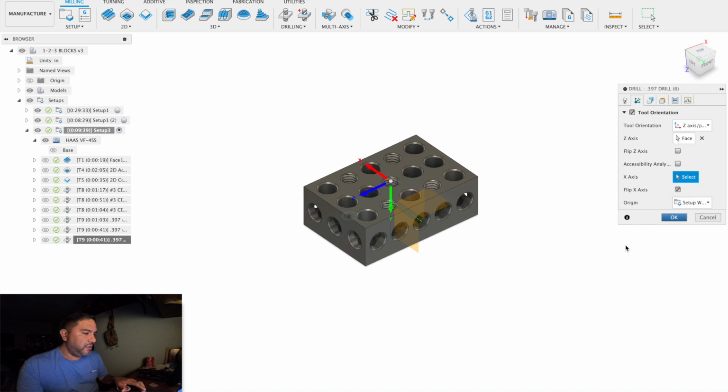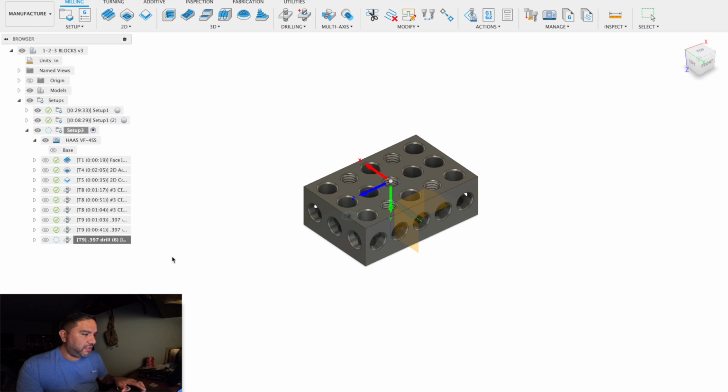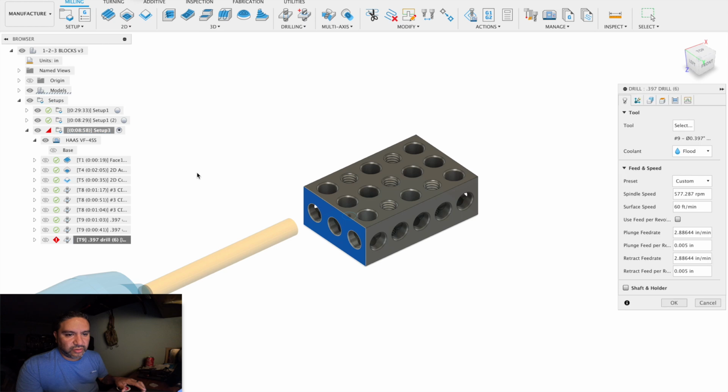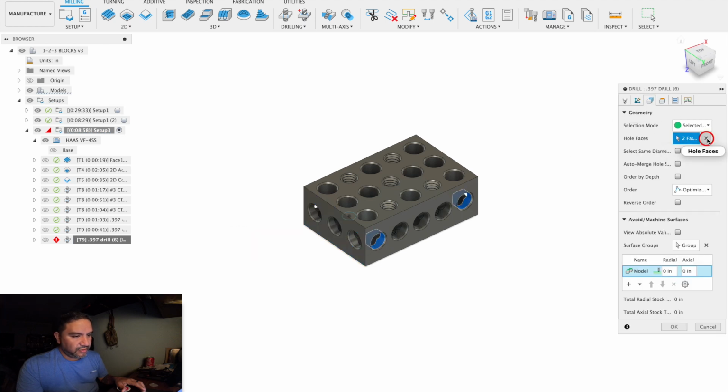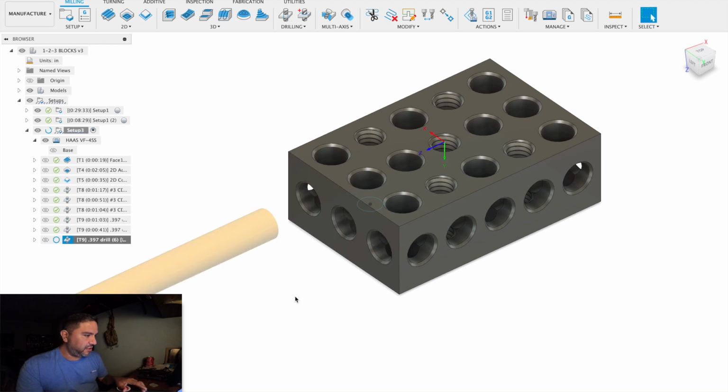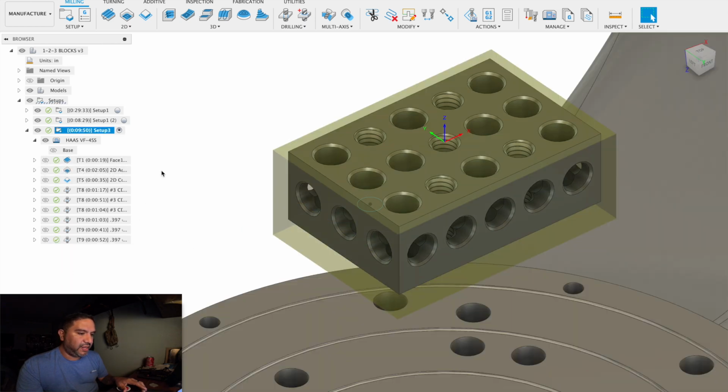Oh. Right click. We got a red triangle because our hole center selection is not correct. So we'll come in here, select the 3, press OK. And the drill's not going deep. This is just for an example. You can change your Z depths however you like. We got all green checks. Press OK. Let's back out a little.